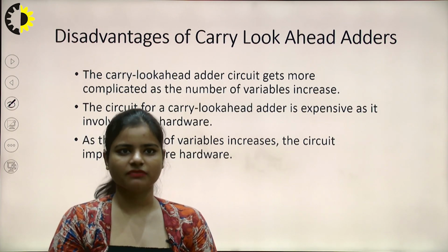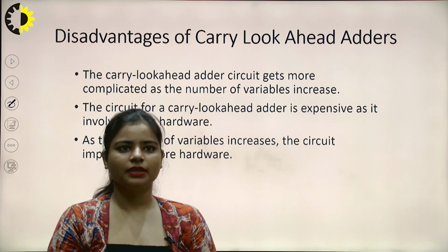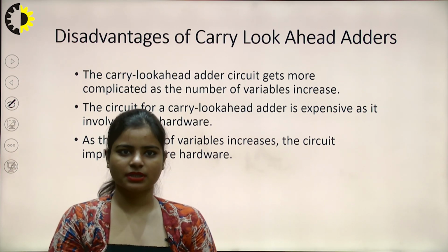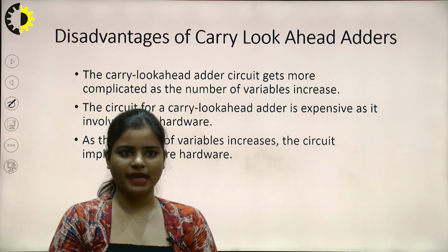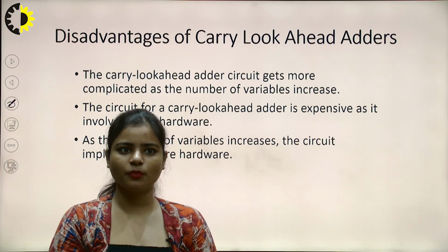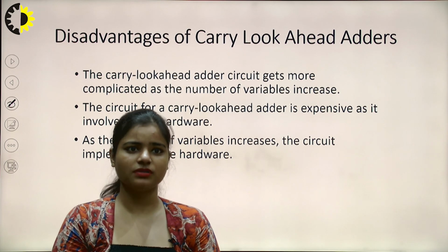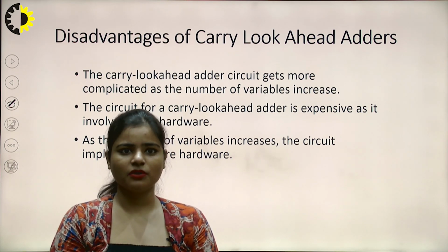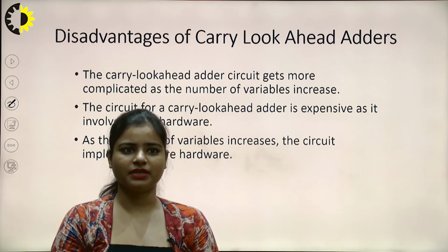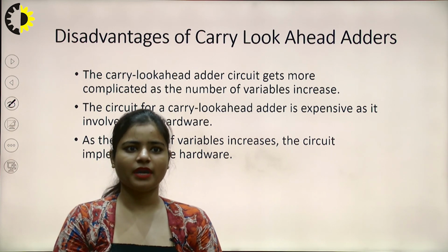And what are the disadvantages of the carry look ahead adder? The carry look ahead adder circuit gets more complicated as the number of variables increases. The circuit for a carry look ahead adder is expensive, which also involves more hardware. As the number of variables increases, the circuit implementation requires more hardware.